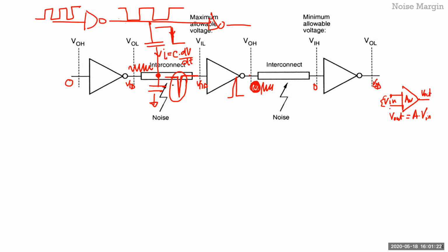There's a lot of voltage switching going on, coupling to everything else. In simulation, in the ideal world, we think it's sitting at 0. If you ever probe into a chip, you'll be almost shocked that this thing is working, that everything is banging around like crazy. It just so happens that you have designed it for all that craziness and it works. It still surprises me to date that it works.